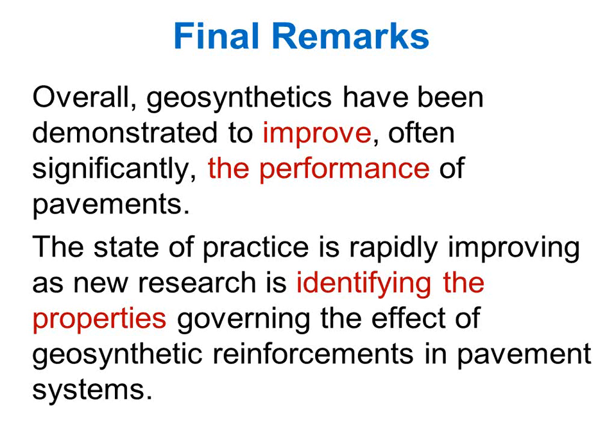Were there any pressure injection lime sections in that farm to market route? No. To be fair, in this site, and this is standard practice in Texas, they didn't do treatment of the subgrade. What they did is they lime treated the subbase of the system.